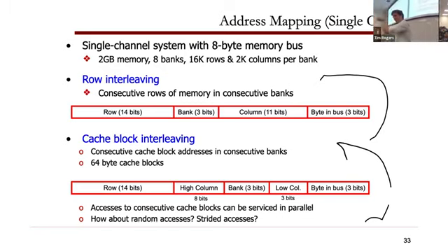We like to touch each of the individual ICs and say, all right, 8 bits of this cache line are here, and 8 bits of the cache line are there, and that's what's happening. Make sense? But physical address mapping doesn't care because it can't individually access the chips, it can only access the ranks. Good question. Other questions? But it's also weird to think about, right? Like your cache block is actually like parts of it are in each of these chips.